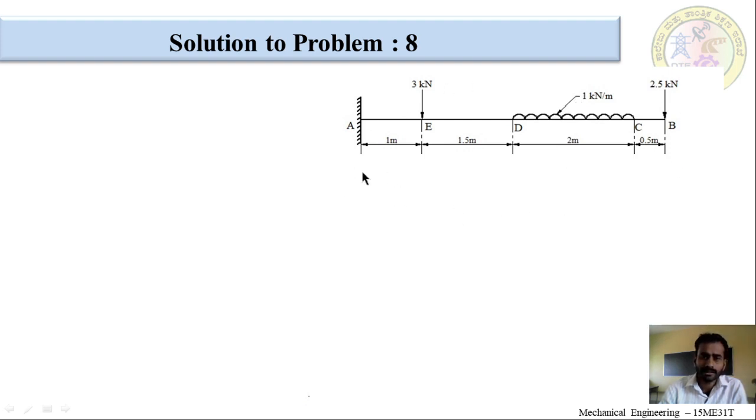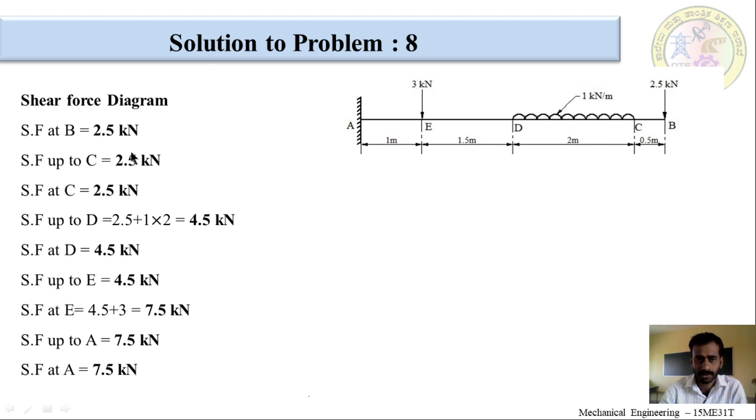So, by considering this, now we have to draw the shear force diagram, and to draw the shear force diagram, now calculate the shear force values. So, from right to the left, we will solve these shear force values. Okay. What is shear force at B?